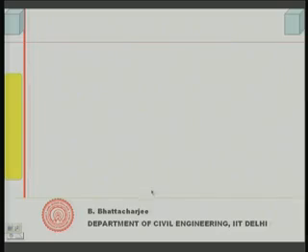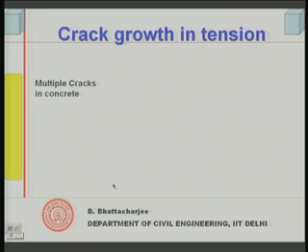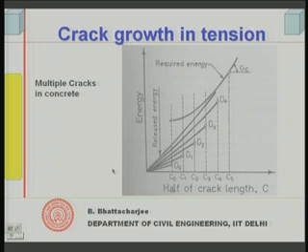Okay. And if we continue with this, we can follow it up. Actually, in concrete what happens? There are multiple cracks, not one, there are several of them. So, the required energy in this case, because there are a large number of cracks and you are creating many surfaces, does not remain linear anymore like previously with a single elliptic crack. There are multiple such cracks, and therefore the energy required will be non-linear like this,